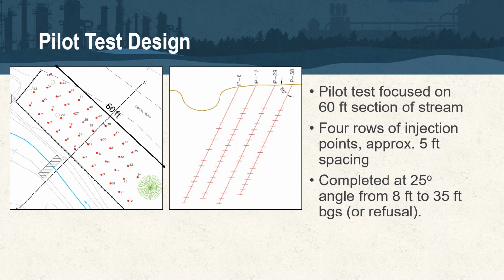And if your groundwater is at 5 feet below grade and you try to inject a slurry on a 10-foot spacing, you're going to have a mess because you've got to put quite a lot of volume in to be able to hit that ROI. In that situation, we would default to a much tighter spacing, probably something on that 5 foot end, the 5 foot range. Then as you go deeper, and so if you're working at 20 feet below grade or deeper, that spacing is going to increase to 7.5, 10 feet.